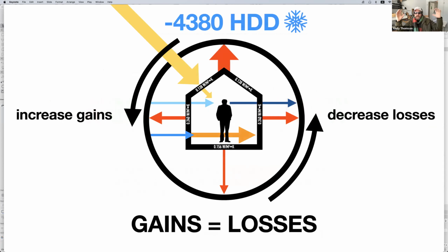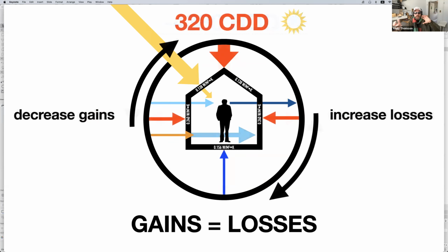So in the overall accounting of the 3D model, you see lots of these diagrams. There's lots of energy and arrows and stuff coming in and going out. But effectively, you're looking at the building as a system, and it's receiving energy, and it's rejecting energy, or losing energy, as the case may be. And you have cooling. In Canada, we have a pretty strong cooling season. And then this kind of all reverses, and then we're trying to dump heat out of the building and prevent gains in the summer. So that's measured against cooling degree days.